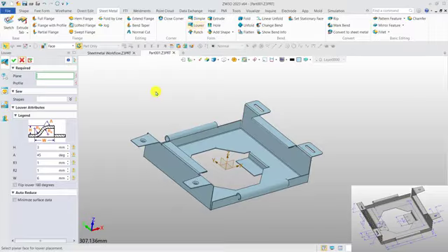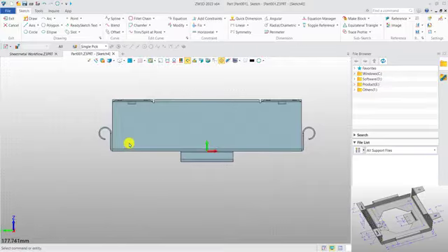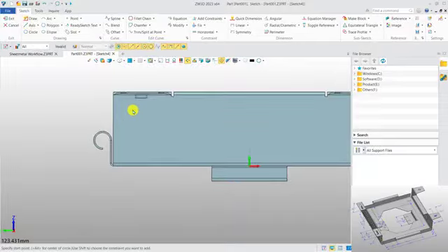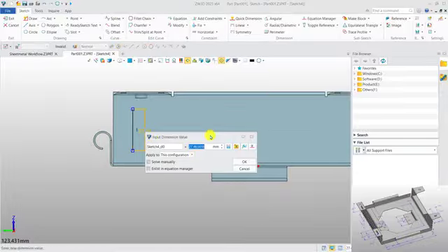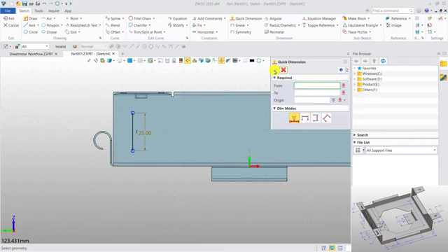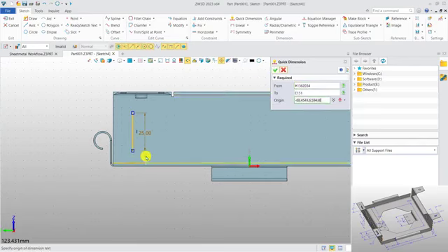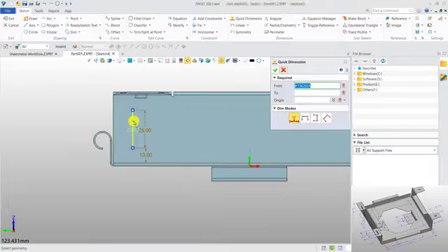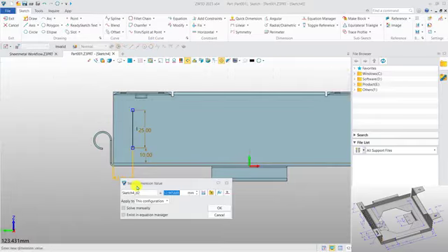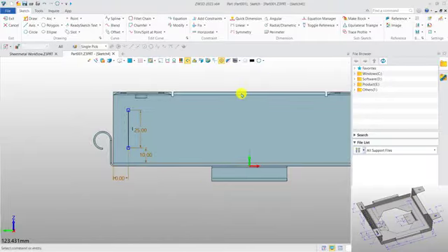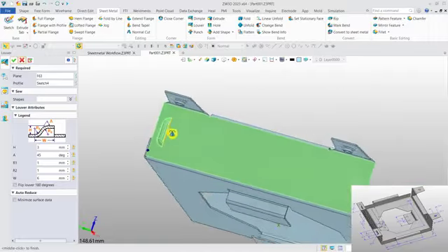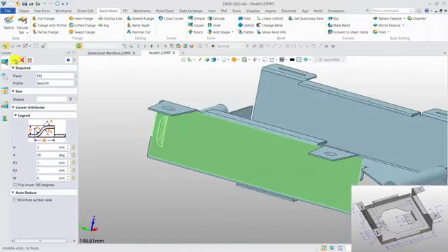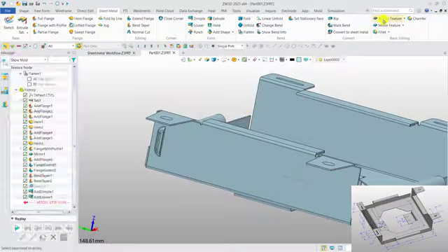Now we can continue to create the louver on the side flange. And we create the path of the louver. Just simply draw a line. And the length, we make it 25, okay. We better make it well defined. Okay, now we can exit the sketch. Okay, for the parameters, we can keep it default. Okay, now we get a result.